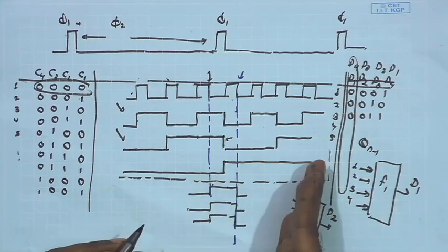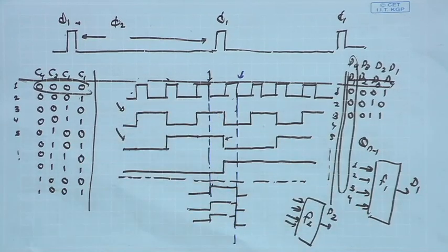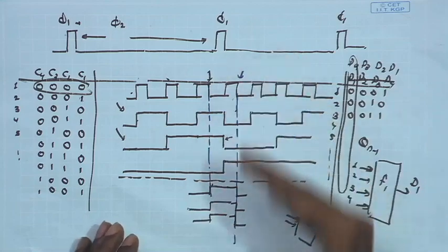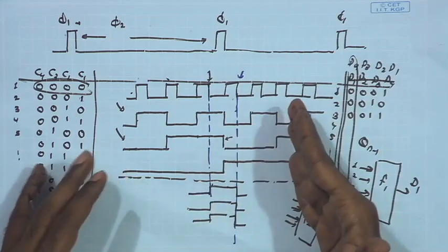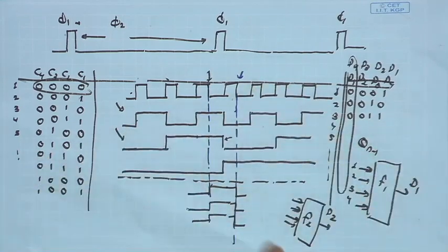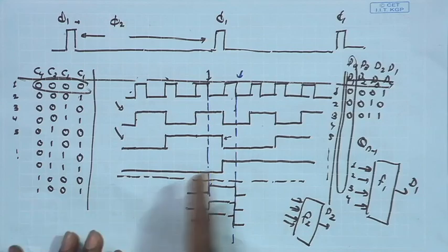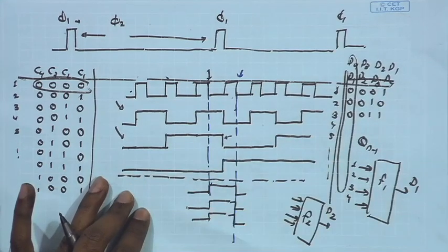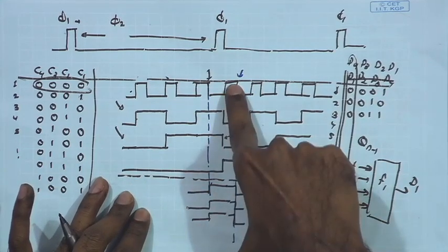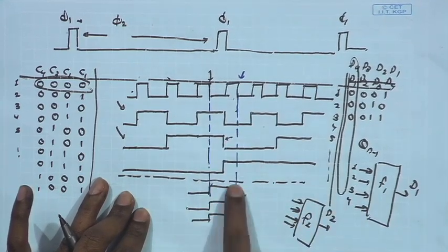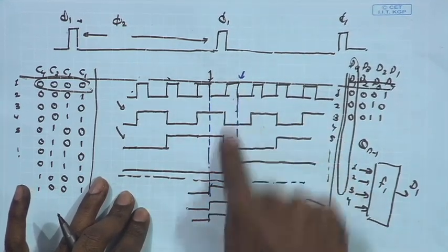So, all of them again get reset to 0 after reaching 1 1 1 1 1, and start afresh from 0 0 0 0. That is automatically happening. We do not need to apply any additional control to do that. So, if you allow it to reach the maximum value 1 1 1 1 1, after that, the next phase, of course, all of them were 1 just before the negative edge over here.